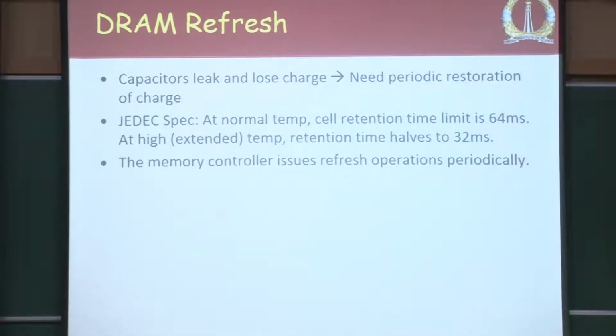Let us talk about refresh a little bit. As we mentioned earlier, refresh is required to ensure that the data stays in the DRAM. Typically a refresh needs to be done maybe once every 64 milliseconds in the current technology. But if the device is hot, at higher temperatures the retention time actually reduces, and it is safer to do this refresh, let us say, once every 32 milliseconds. This is device specific, and the manufacturer is going to tell how often the refresh has to be done.